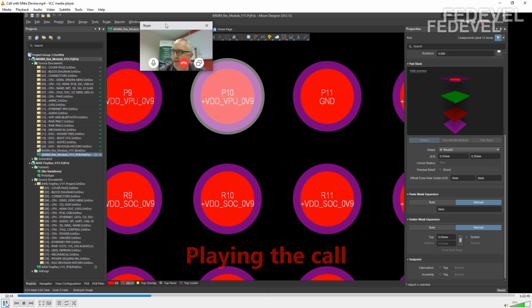So if the PCB is, let's say for instance, in a drone and it's going to be on the ground in a high temperature country, and then it's going to go into the sky, the temperature is going to drop quite dramatically. It's that thermal excursion and pressure on the PCB that is going to make the PCB start to expand and contract.